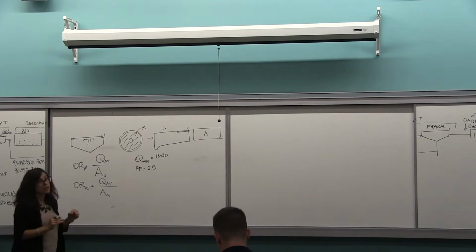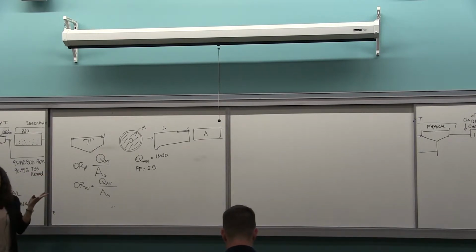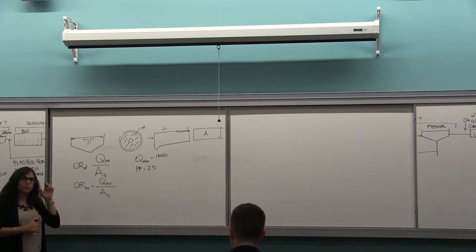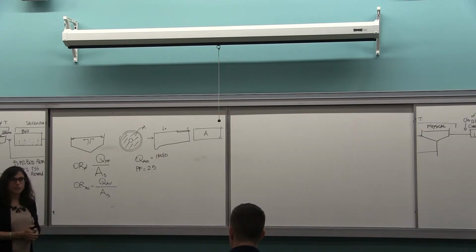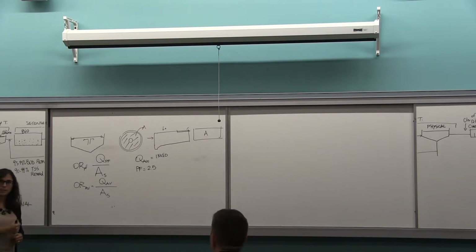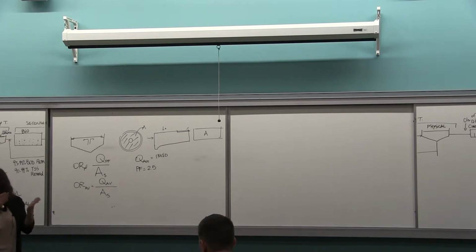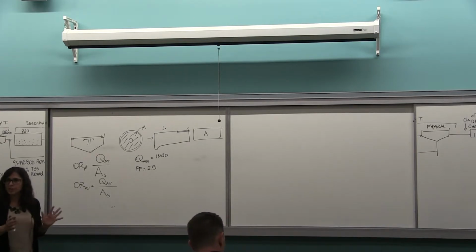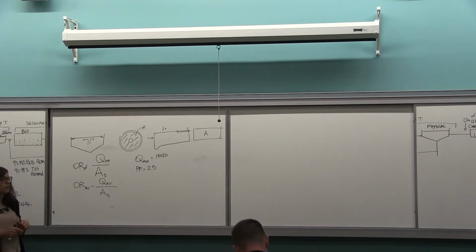And the design criteria, so these are set values essentially by the, in New England will be the, can't think of the name, the New England Pollution Control, like they have a manual that will give you the guidelines, so what is the range of overflow rate.